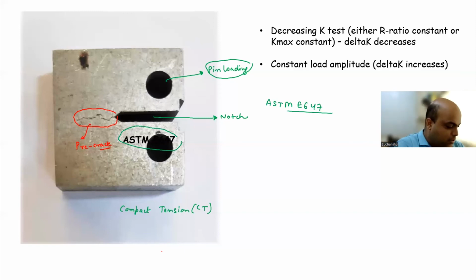Now I have brought tensile specimens also, so different kinds. This is the rounded tensile specimen, but this is a threaded one, so there will be threads where you need to fix this specimen. Another one, again rounded, but here you have to grip it. The first one was a threaded one where you have to fix it. Here you have to grip it, so there will be two grips and then you can do the tensile test.